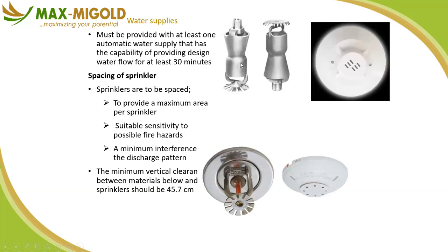And here we're just looking at the sprinkler head. Again, this is an NFPA standard requirement, which may not be what you want to do. But we put it here to say that there is a minimum spacing based on the umbrella that will be formed from the sprinkler head that has been selected, based on the material that needs to be protected. So what are we even protecting within this space? How much water coverage do we need?